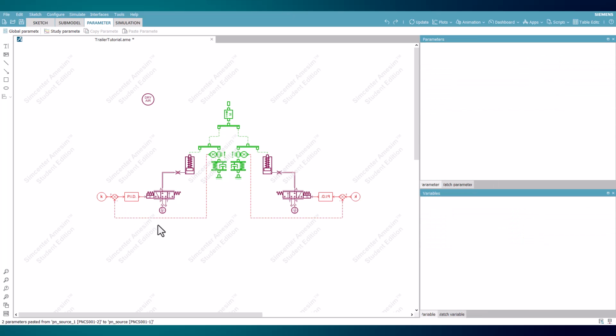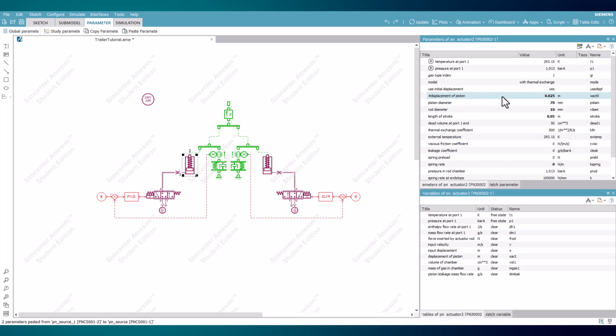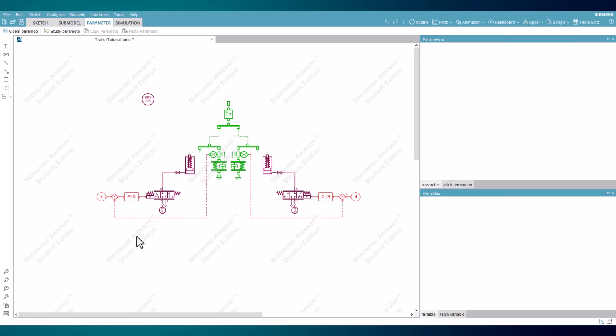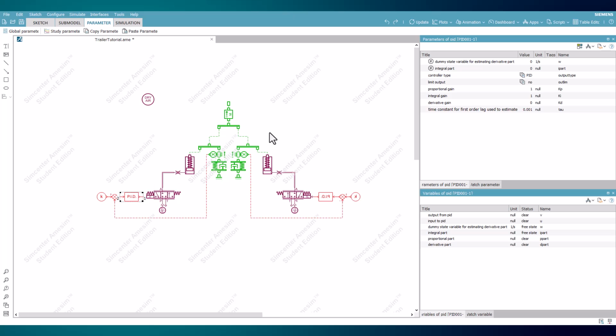A maximum error value will be 0.025, as that is when the piston is completely closed and leaving the mass only on the suspension. To have a maximum value of 40 from the product of 0.025 and a number, that number must be 1600 and will be the proportional gain value.